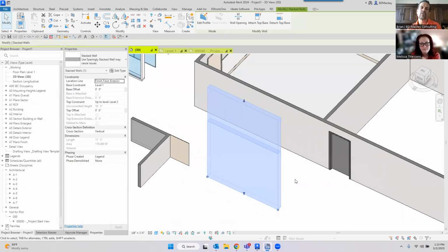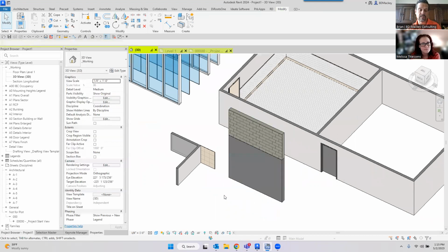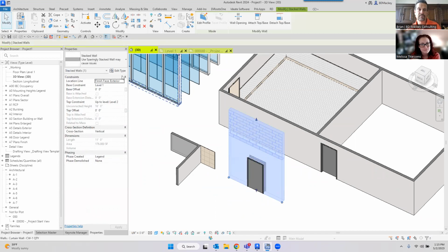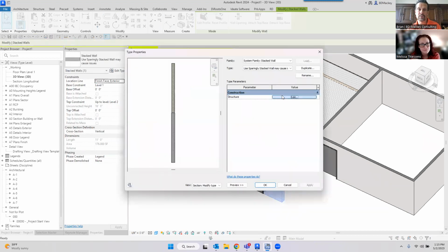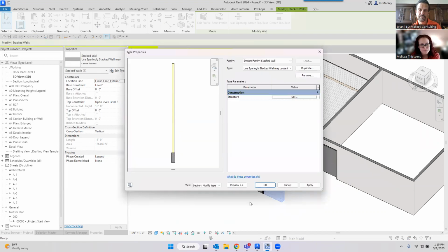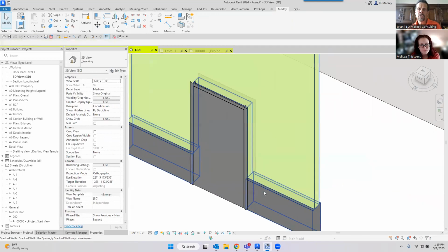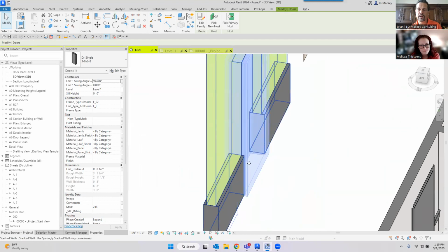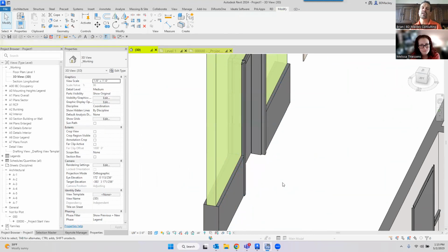And the reason why I'm going to undo that is the other reason why I'm not a big fan of this is, let's say you go in here and you put in a door, and go edit this wall type. You can see I don't really use these, so I don't really have the structure. We're going to go make this bottom one like 2 feet tall. And we're going to change the above one to be something thinner. So the thing you're going to start to notice is that the door that I hosted, since the door does come in here, is going to pick up on the thickness of the base wall by default.